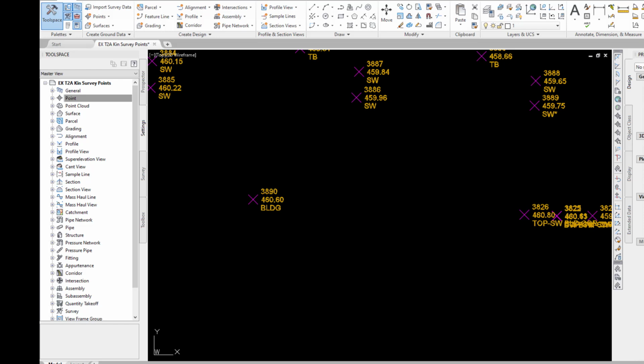At times, additional field survey points may be added to the drawing, or additional points may be created on the drawing. These points need to be added to a point group. For the purposes of this video, 2 additional points will be created between point number 3890 and 3826.